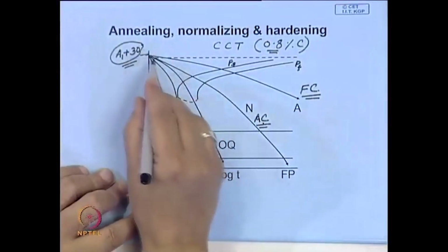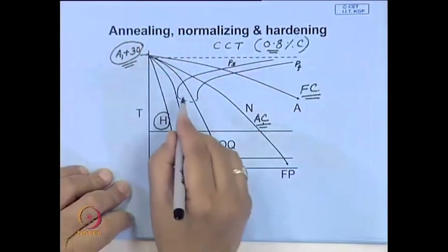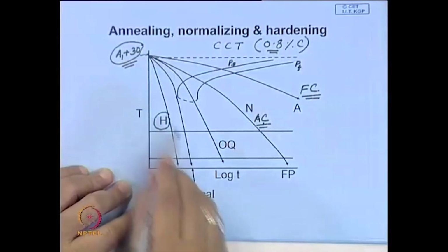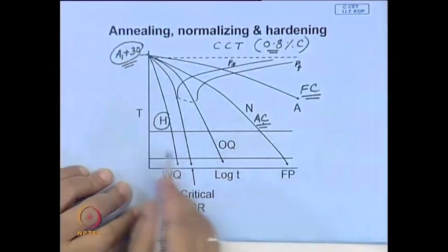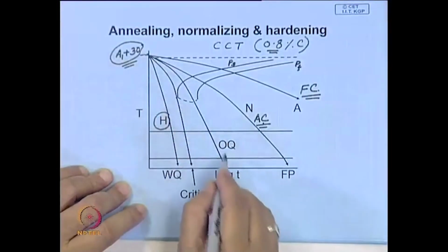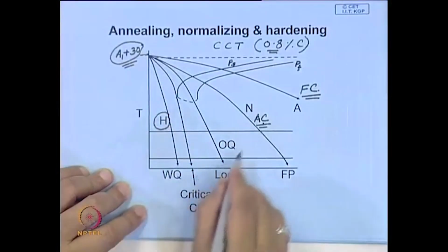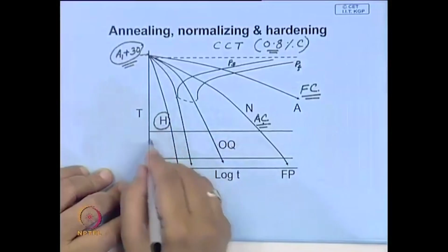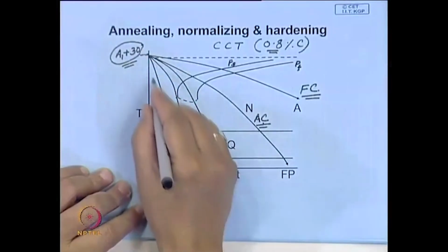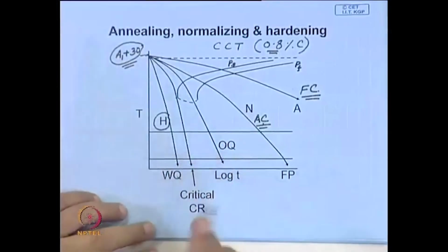We have mentioned time and again that in the continuous cooling diagram of plain carbon steel, we do not get bainite. Now, if you adopt another method of quenching, say oil quench, maybe this is the cooling curve somewhere here. Mind you, we will come later to what determines the rate at which you will be able to cool a job.